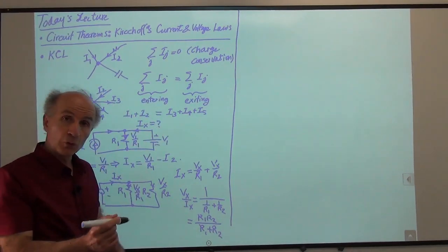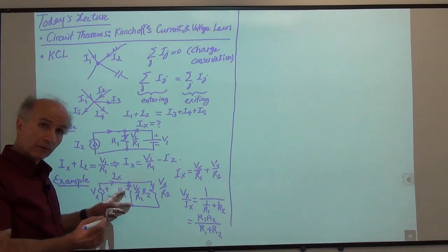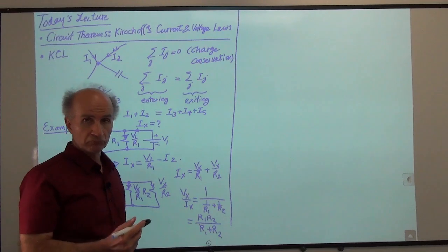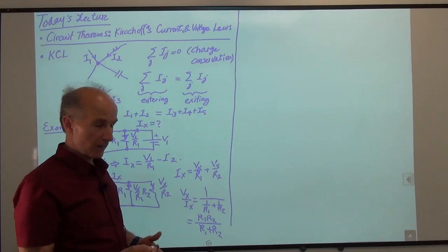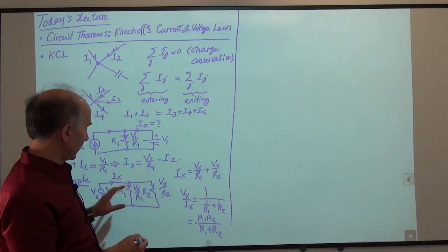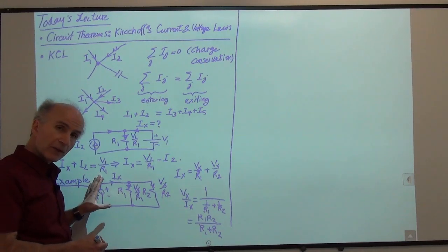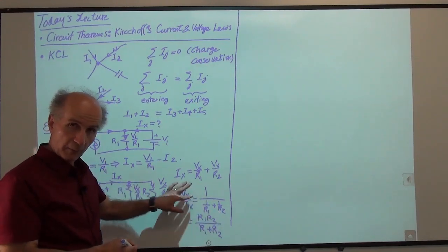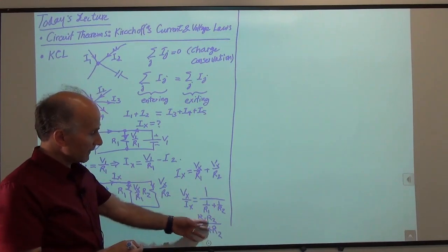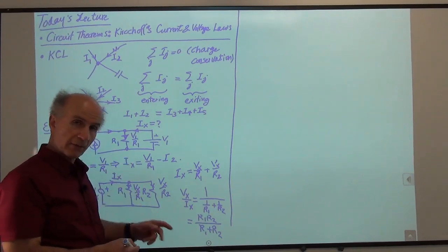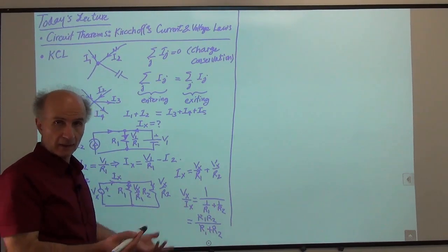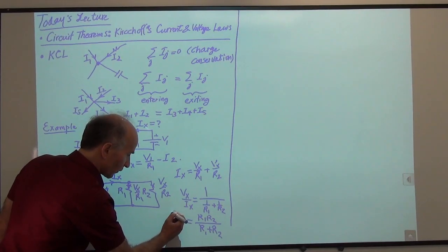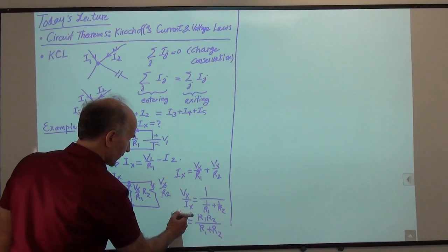All right, so two resistors in parallel are equivalent to one of value R1 R2 over R1 plus R2. So that's easy to remember. You might have seen this in physics, that you would say the inverse of the equivalent resistance is equal to 1 over R1 plus 1 over R2, because that would be the inverse of this. But this is actually simpler, so often for only two parallel resistors, we write the result like this, and then it's easy. So that would be our equivalent resistance for only two parallel wires, right?